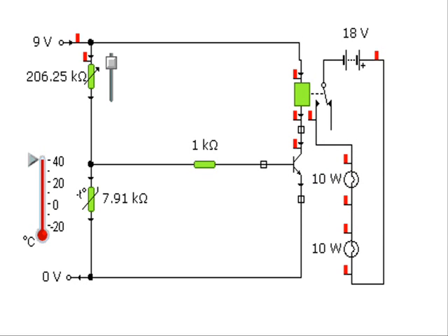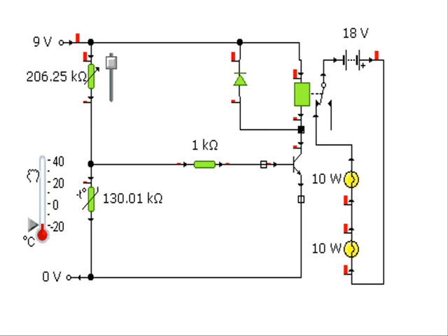To protect the transistor from back EMF, we use a diode. And the diode goes in across the relay with a wee arrow pointing up the way. Now we can switch away to our heart's content, and back EMF will not destroy the transistor.